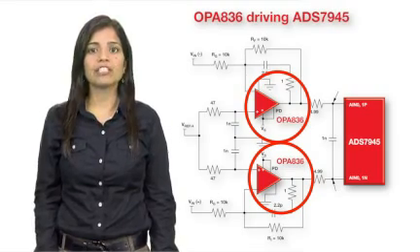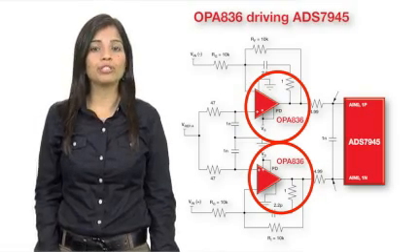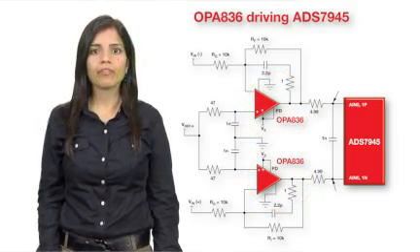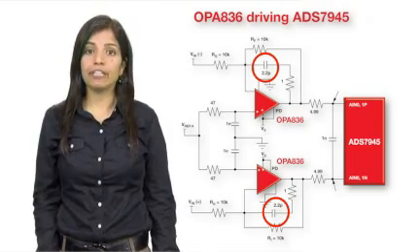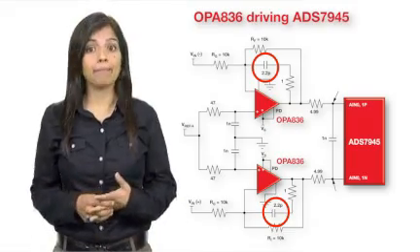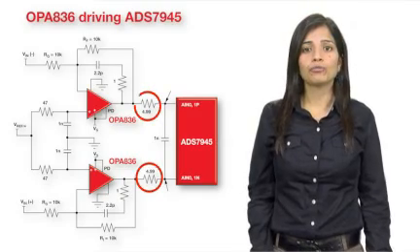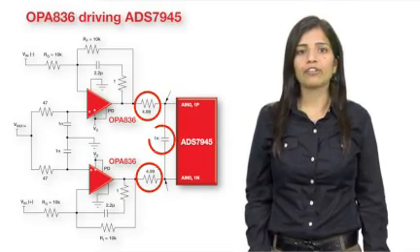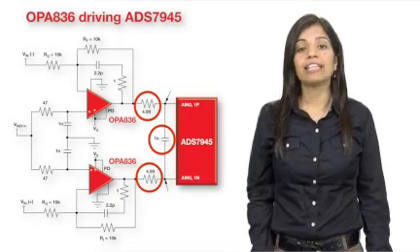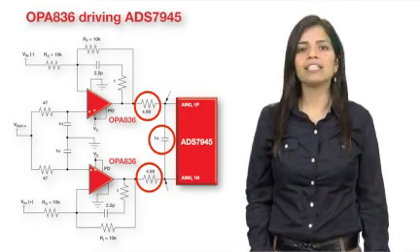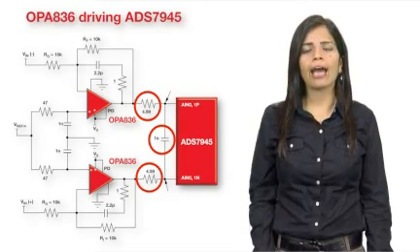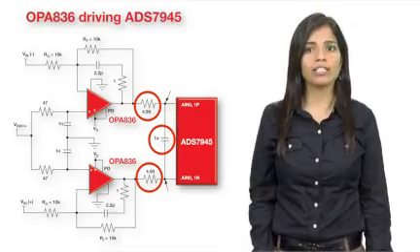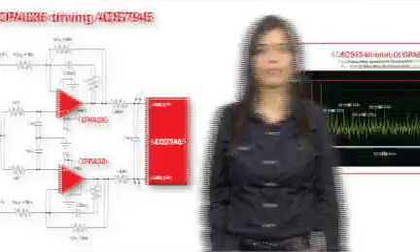The circuit here shows 2 OPA836 op-amps configured as a differential amplifier, each in the inverting gain of -1 with RF equal to RG equal to 10 kilo ohms. A 2.2 picofarad capacitor in the feedback helps to minimize gain peaking and noise. The two 4.99 ohm resistors and 1 nanofarad capacitor at the ADC input provide a single real pole filter to limit noise, and more filtering may be required depending on the application.